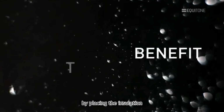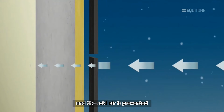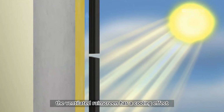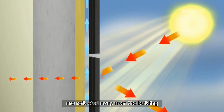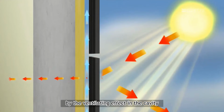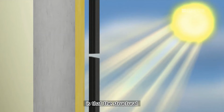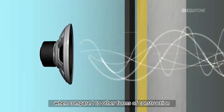Placing the insulation on the outer face of the structure results in a number of benefits for the building. Notably, in wintertime it keeps the building warm and the cold air is prevented from affecting the building structure. In summer, the ventilated rain screen has a cooling effect when outside temperatures are high. Most of the sun's rays are reflected away from the building. Heat that passes through the panel is partially dissipated by the ventilating effect in the cavity. An additional benefit in controlling temperature is that the structural movement of the building is minimized. Acoustic performance of the wall is increased when compared to other forms of construction.